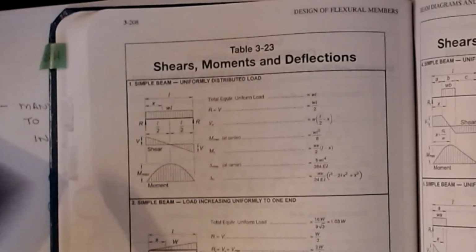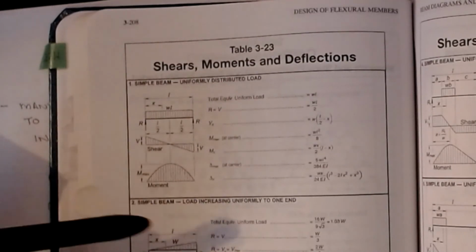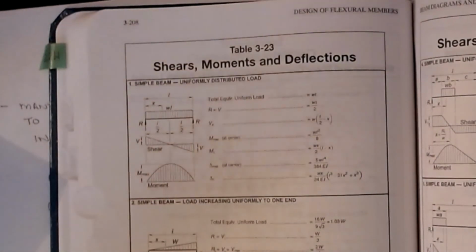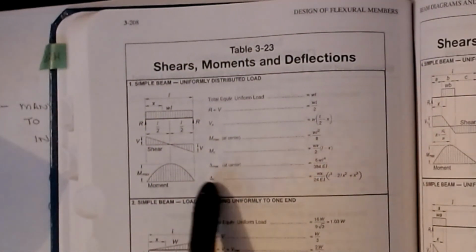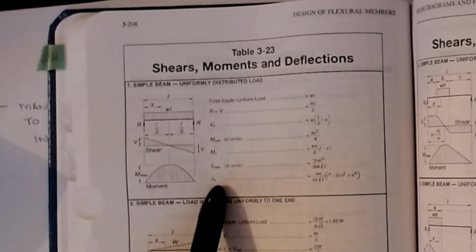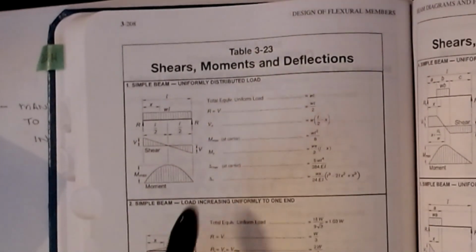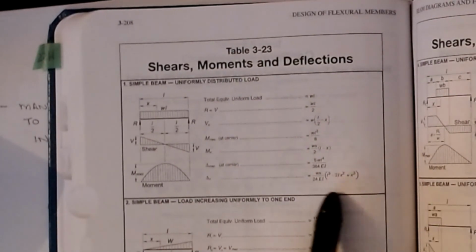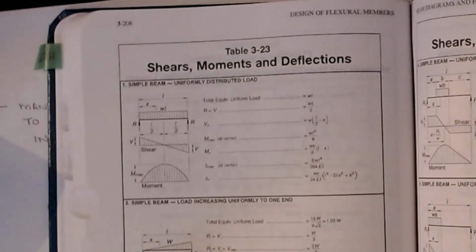One thing to recognize is that the AISC manual does not give you the slope directly. Okay, but what they do give you is a function for the displacement as a function of x. And if you remember, if this is my y equation, the slope is the first derivative of this. So I can take this equation, take the first derivative of it, and I now have the slope equation. And I have that for a wide array of cases.